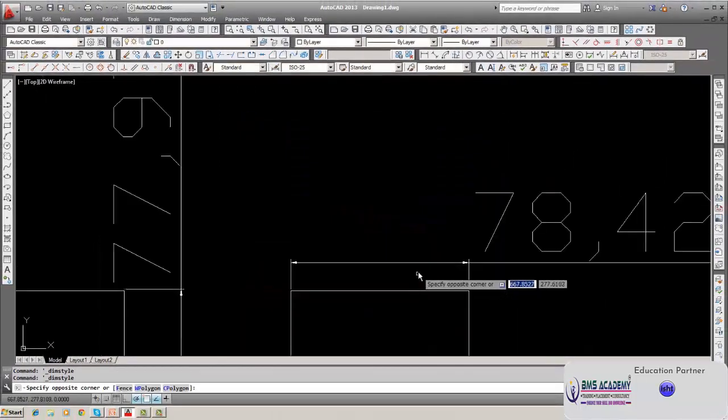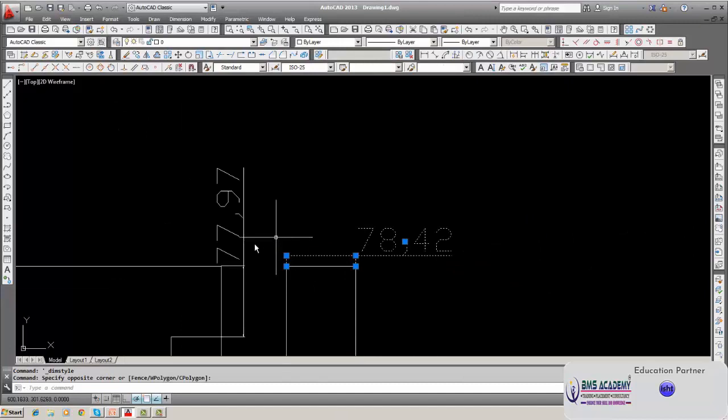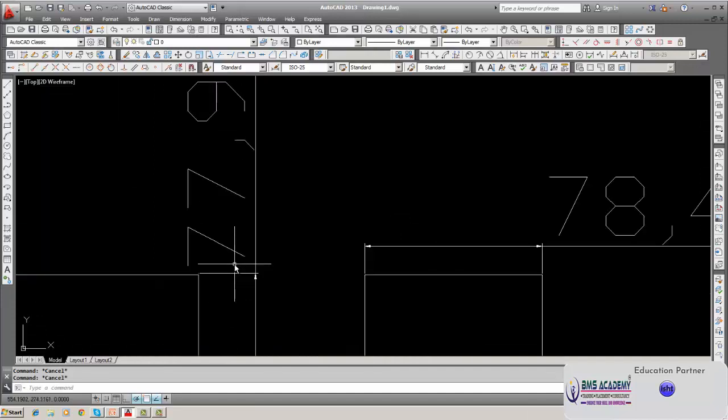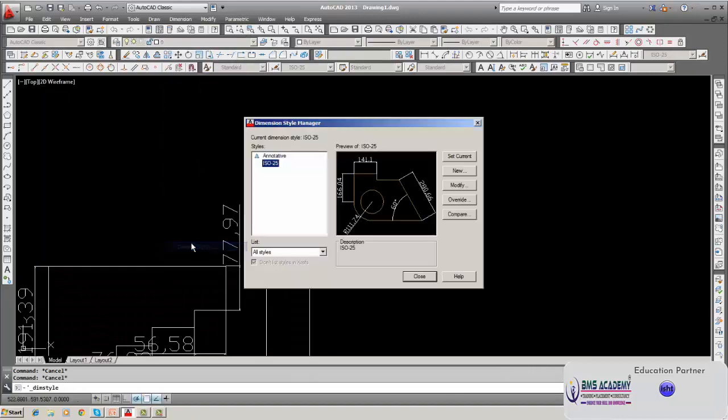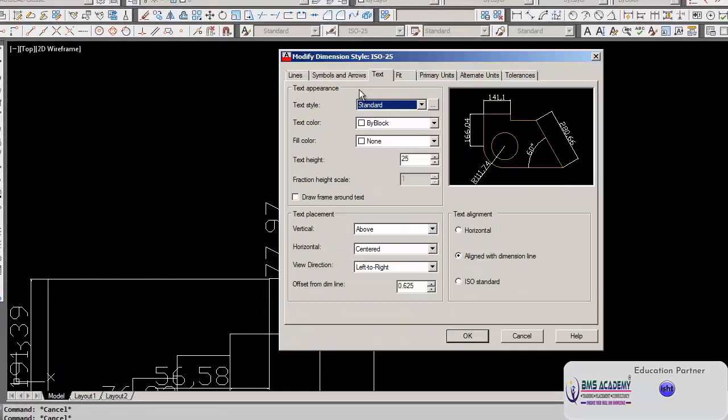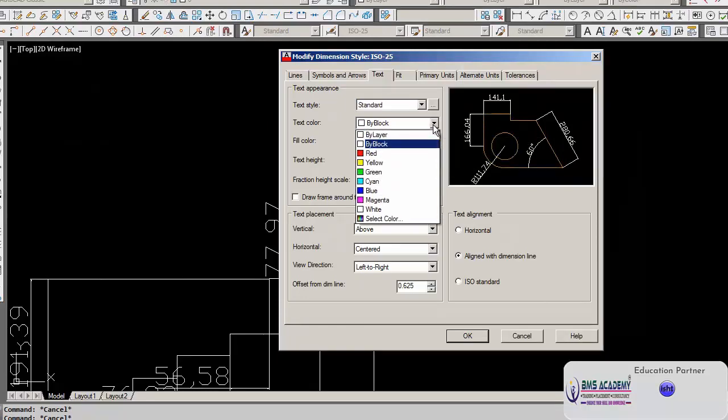So the size has become bigger. See, all the sizes have increased now. And now we have to set other things also. But now see, the arrow mark is small. So we have to set the arrow mark also. Go there. So we have text size and fraction height, that I will come to later on. And block, we will select the layer. Whatever layer you have for dimension, the same layer, the text matter will be there. I will come to that.